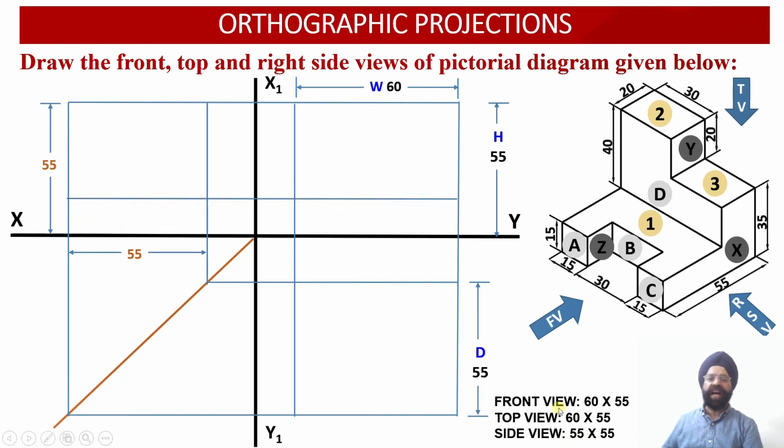Right now let us start with the construction of the front view orthographic projections for the solid. So let us observe the solid from the front. We work out that there is a lower web, or we can even call it a bottom block. Corresponding to this bottom block, we have a height equal to 15 millimeter. So the height of this bottom block happens to be 15 millimeter. Here we have marked the height of the bottom block as 15 millimeter.